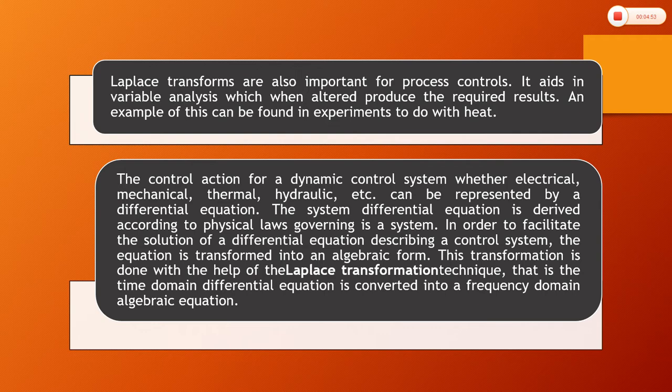The control equation for a dynamical control system, whether electrical, mechanical, thermal, hydroelectric, etc., can be represented by a differential equation. The system differential equation is derived according to a physical law governing the system. In order to facilitate the solution of a differential equation describing a control system, the equation is transformed into an algebraic formula, and this transformation is done with the help of the Laplace transform technique. That is, the time domain differential equation is converted into a frequency domain algebraic equation.